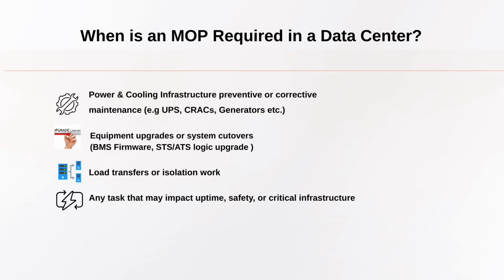They're also critical during load transfers and isolation work. Whether you're switching load from utility to generator, isolating UPS output to test a breaker, transferring mechanical loads between CRAC units, or racking breakers in and out, these are moments where a mistake could take down a system.